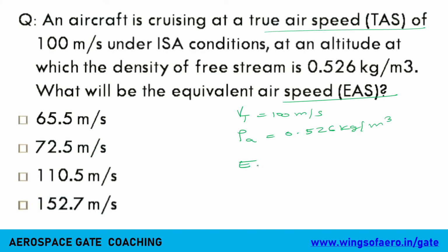You have to find the equivalent airspeed. Then what is the density at sea level? You have to remember 1.225 kg per meter cube.